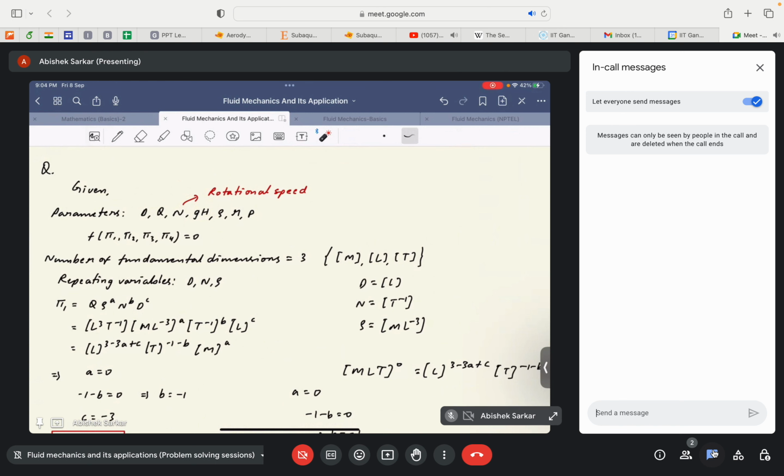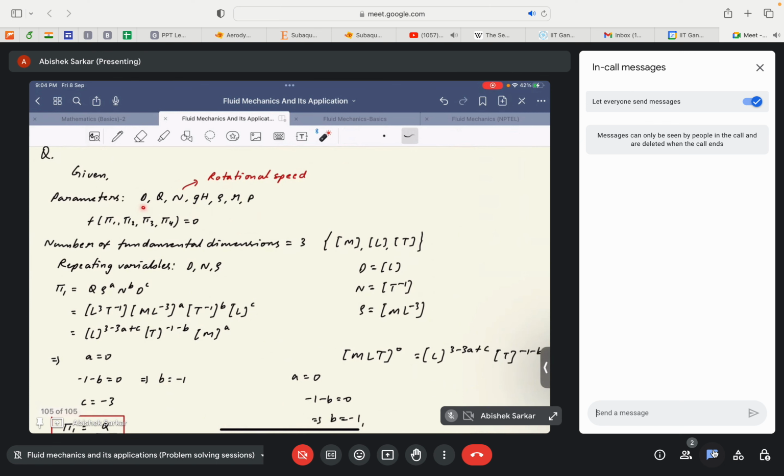These are the parameters upon which our current problem depends. So from this we get an idea that since there are 1, 2, 3, 4, 5, 6, 7 fluid flow parameters, and because we are only dealing with a simple fluid flow problem without any heating or electromagnetic force application, at least within the control volume, the fundamental dimensions would be mass, length and time. So the number of fundamental dimensions is 3, so we will have 4 pi terms.